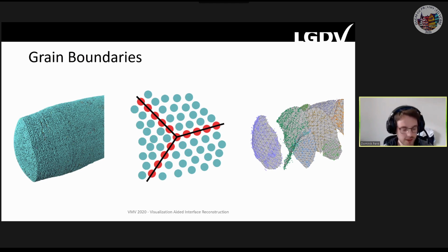Another interesting property you can see in the schematic in the center is that the emerging boundaries may intersect in a non-manifold fashion. For example, if you imagine you extract the Y outwards of the screen to get the boundary, you have this Y junction, and in geometric processing terms, this is not manifold. So it's not a manifold triangle mesh anymore.